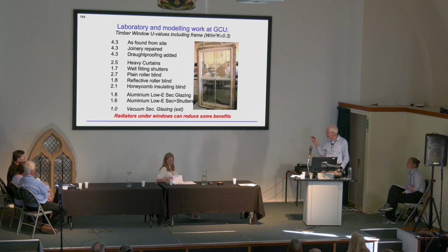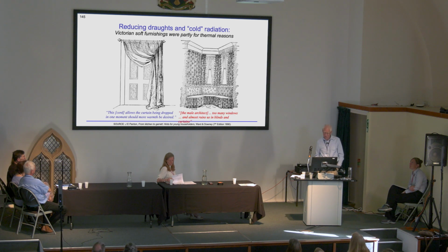Now, Salford did some work on their energy house and said, this is all very well, but it's in a climate lab. And often in British buildings, you have a radiator under the window. And of course, you have curtains over the window and a radiator under, and the air goes up behind the curtain. You might get quite the opposite effect. So you have to be a bit careful. In all this stuff, there's a subtlety. These are only just order of magnitude figures. In a particular context, things may be different.